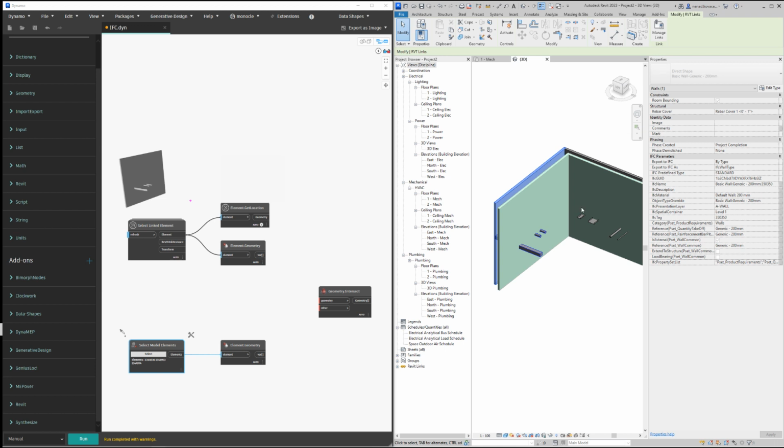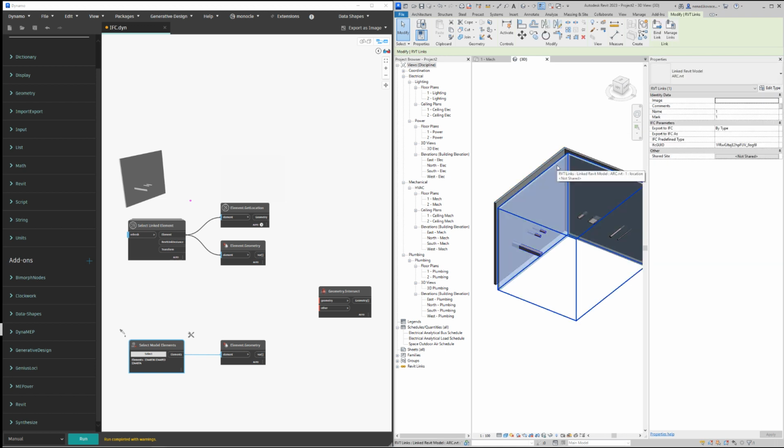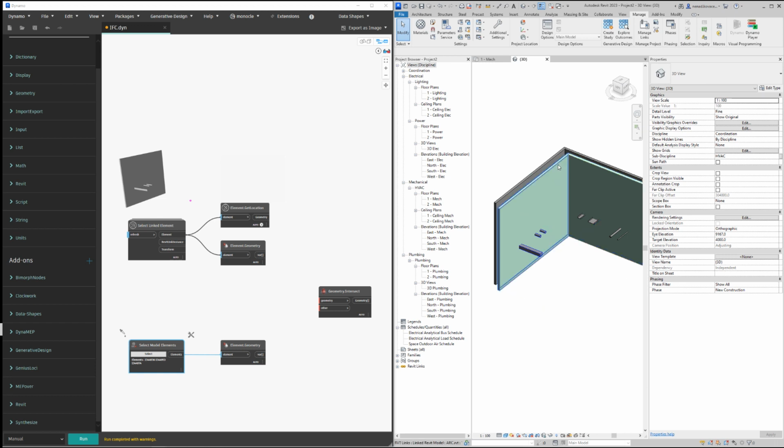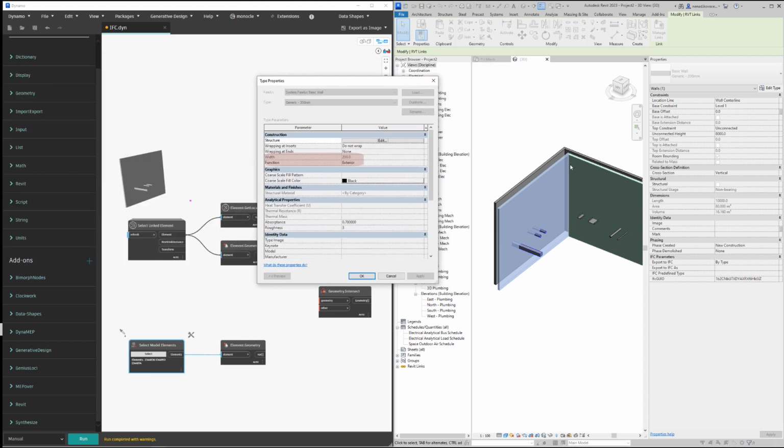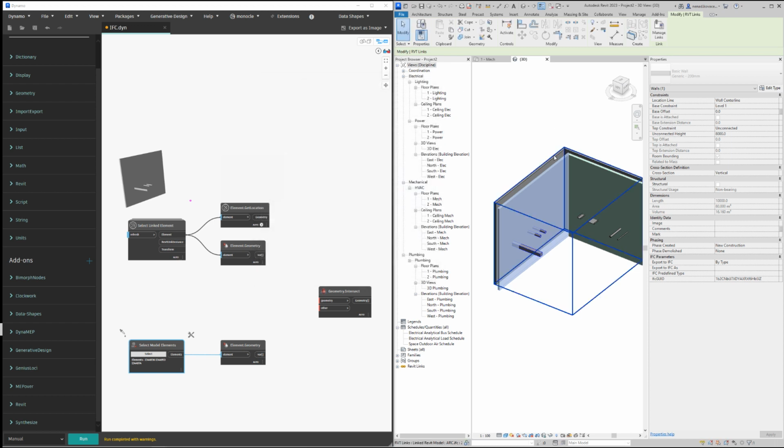And that's it. From another perspective, if you want to find the thickness or width of the wall, and the element belongs to a Revit element, then you can read the width of the wall. And you don't have that in the IFC.